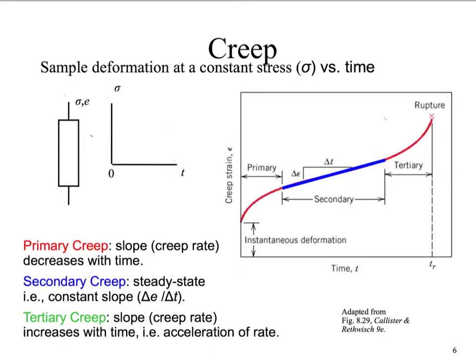Now we can talk about creep, which is another method of mechanical failure in a lot of materials. Creep originates from static loads that are maintained at elevated temperatures in the material. They're time dependent, they're permanent, and they're undesirable, and they often act as limiting factors for the lifetime of a part. They're observed in all materials, but we look at them a lot in metals.